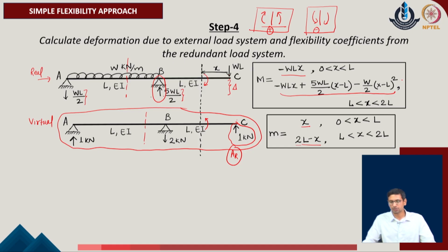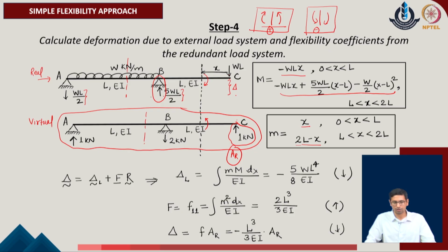Now, once we have the moment expressions of the given system, we can evaluate the amount of the displacements in the direction of the given load, which is the delta L component. We can also evaluate the flexibility coefficient of the given system, and using these two parameters, we can now specify the condition of compatibility in the given problem.